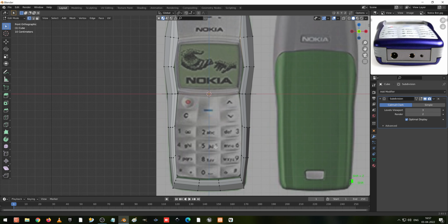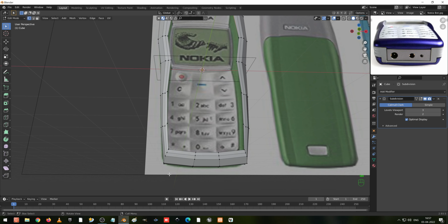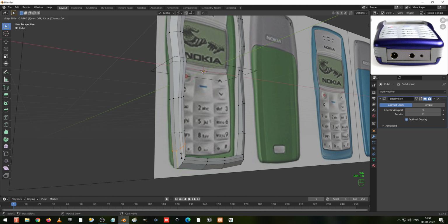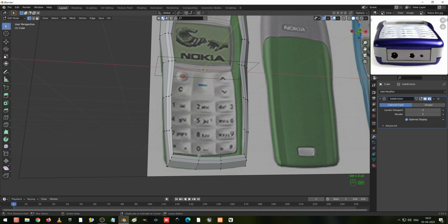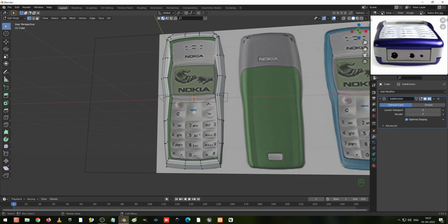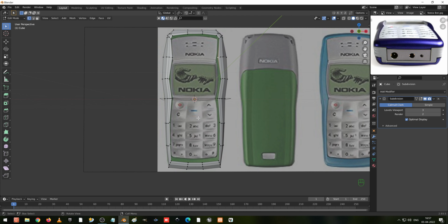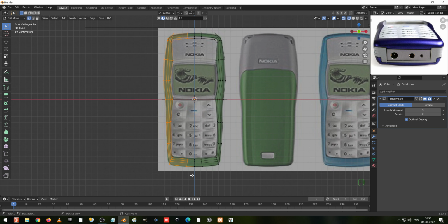So after doing this, we have got a good shape here, but you can see it has one sharp corner here. Select this, and I'm going to create two edges like this to bring that shape. So before that, it didn't come out correctly for us. I do one thing here, and here I create one edge loop. Go to front view, and I'm going to delete all the vertices on one side, and I'm going to do the mirroring for this.